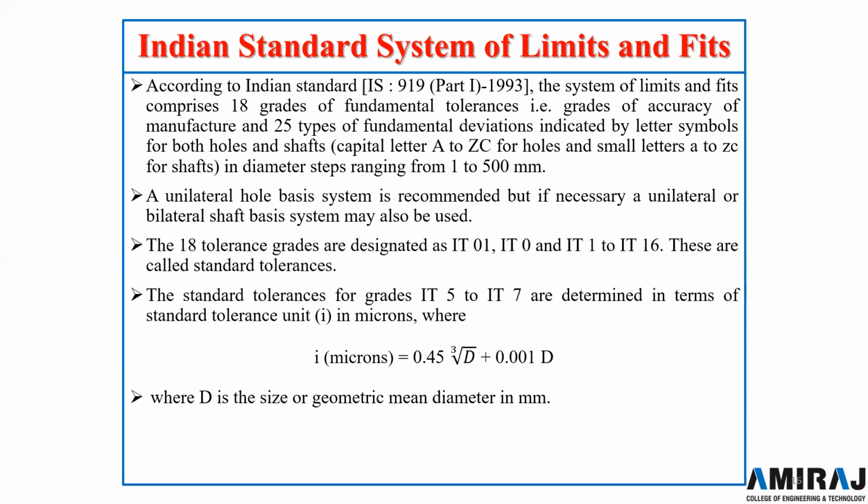The system of limits and fits comprises a total of 18 grades of fundamental tolerances, grades of accuracy of manufacture, and 25 types of fundamental deviations indicated by letter symbols for both holes and shafts. Capital letters A to ZC for holes and small letters a to zc for shafts.